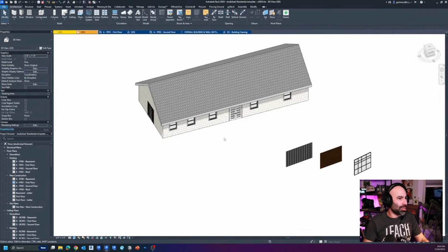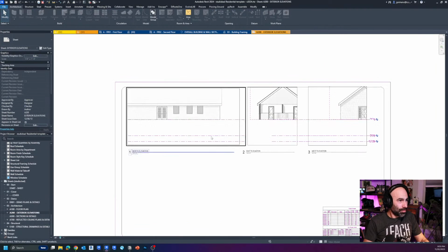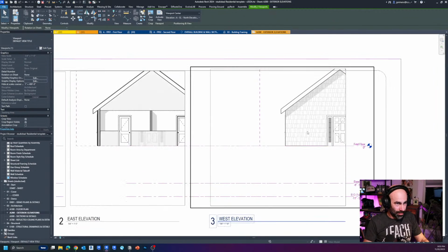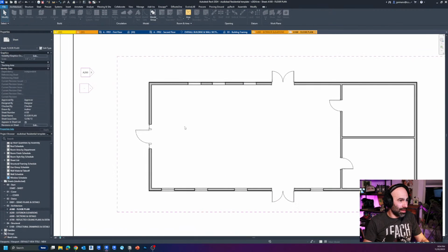The last thing I wanted to show you here was, if I go down to my elevations, what you'll notice is that having the shadows, having the visibility parameters set in there, you do have to modify it sometimes. So if you're using depth queuing, for example, depth queuing is a really hard thing to have templatized, mainly because it's based on levels of where the building exists, and every building is a different shape or size. So that's something to keep in mind.